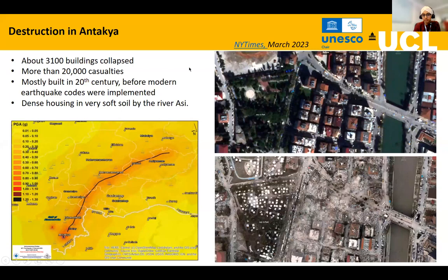They had deficiencies for the kind of earthquake that occurred. Even the PGA that was recorded in areas such as Antakya is higher than the highest seismic zone designation, such as 0.4 g, which is the cause of the heavy destruction that was experienced.